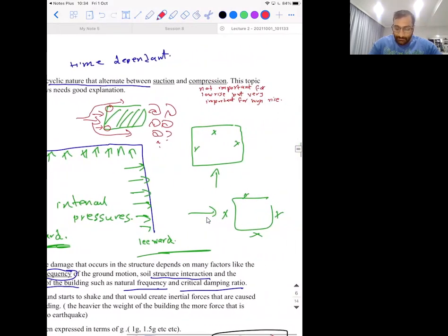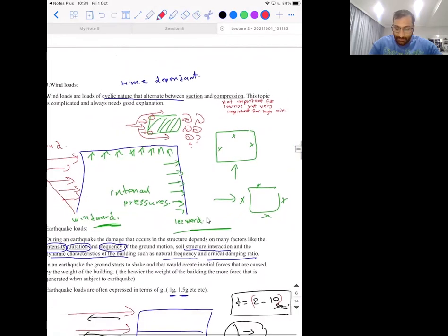Now let's talk about some phenomena. Just a point, that this is not important for short buildings. Anything three floors down, you're not considering wind as much, unless it's something unconventional, long span, and has a hole in the facade, then maybe you consider wind load. But for skyscrapers, for high-rise buildings, no, it's very important. It's actually detrimental. It's a design parameter. It's a main design parameter.